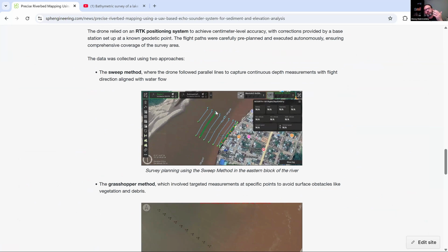You can plan the mission to pull the sensor out from the water and start here again, or you can fly a kind of zigzag mission. So when a segment is aligned with the flow, you will get good data. In the opposite direction, the vertical orientation will be too far from vertical, and data will be automatically rejected. So yes, you can use our system.